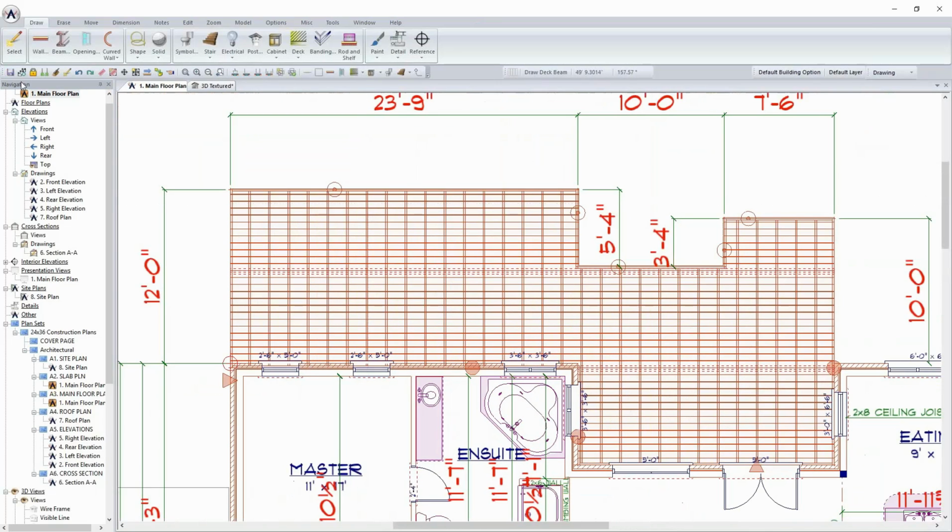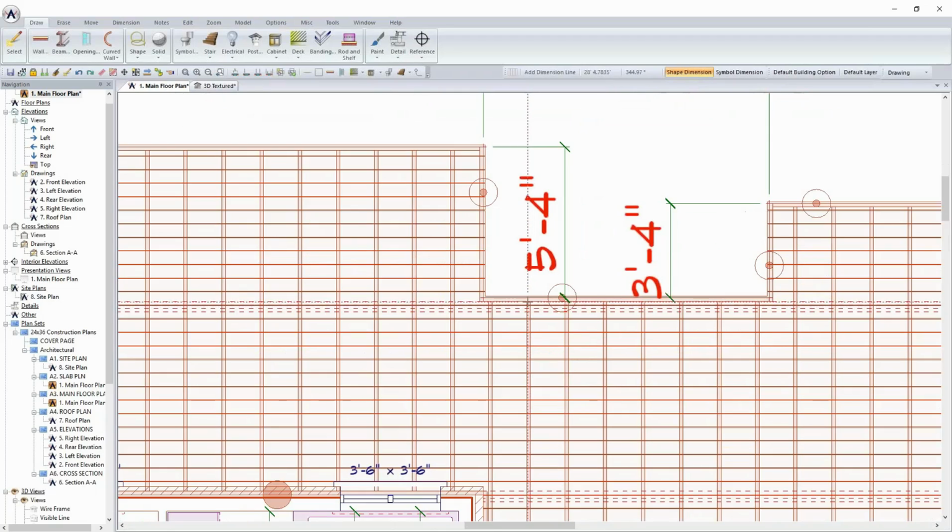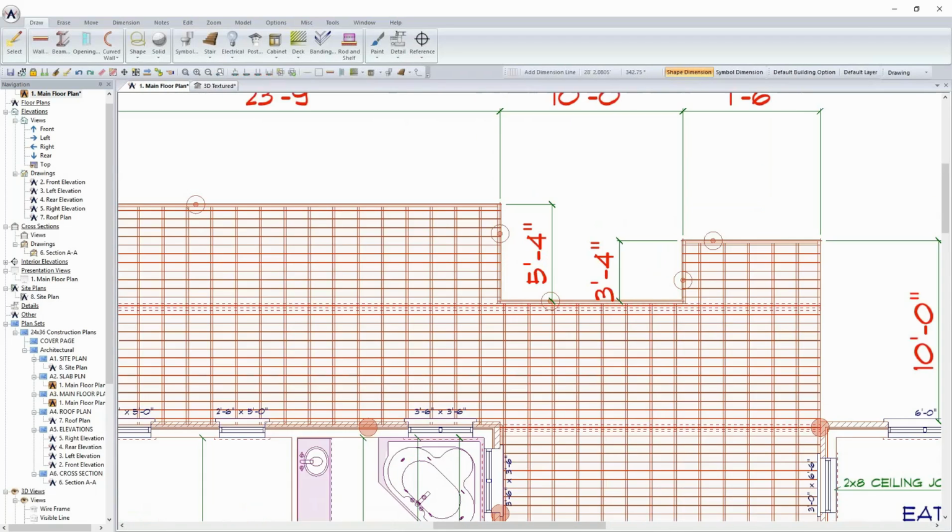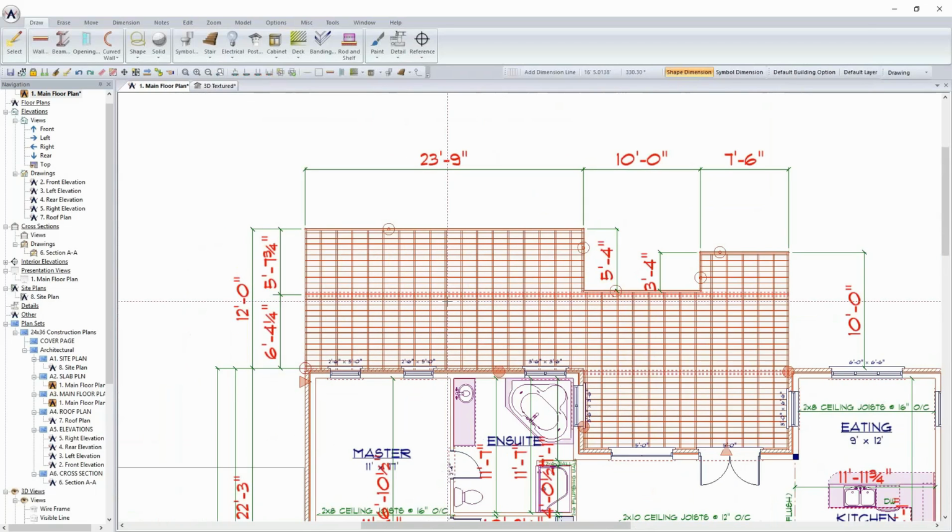With that done, the next thing that we will want to do, and of course I could pull dimensions off of this. You can simply dimension that into place. I just pulled a simple single extension off of there, and then I could certainly pull dimensions off. It's placed at this stage visually so that the edge of the deck beam is right against the ring joist at this point. So that's why the dimensions are what they are, because of how I set this up, and I could edit these and adjust it accordingly as well. All right.